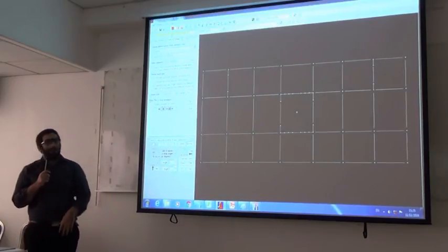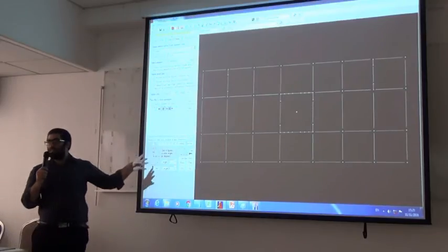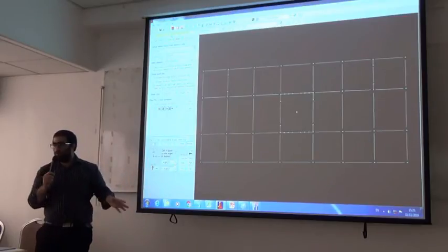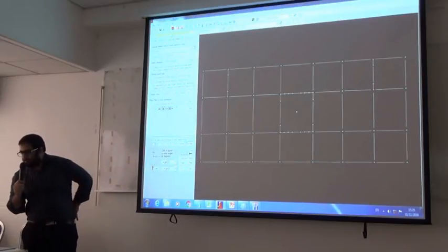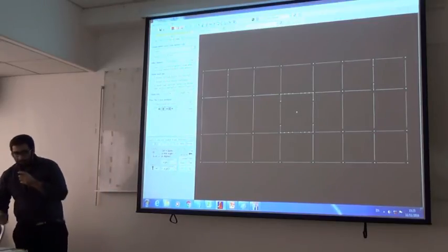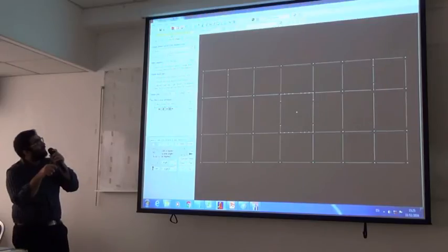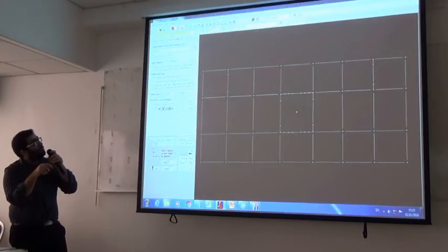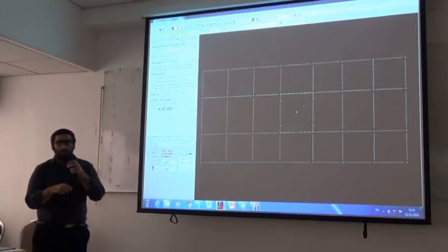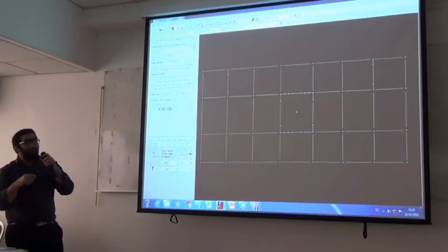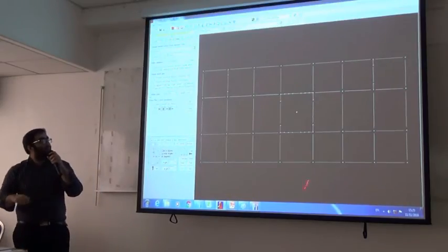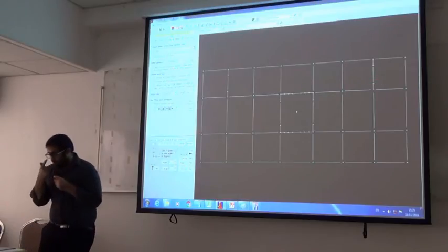So if you guys want to open this tab, you can open it also, and try to follow so that you can get the same plot as I am getting. The tab over here is the moment and shear diagrams tab, and then you need to select the line of elements option. Line of elements basically means that multiple element results will be shown together. A single element means that you will have a single element result, right?